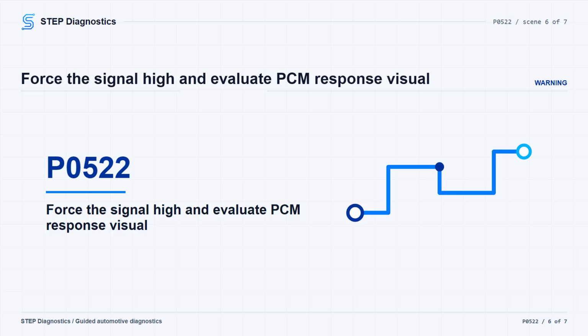Turn the ignition on and read codes with the scan tool. If the scan tool shows the expected sensor signal circuit high code with the jumper in place, the PCM saw the forced change on the signal circuit. At that point, the diagnostic path calls the EOP sensor faulty. Replace the sensor, then verify the repair and confirm the code stays gone.